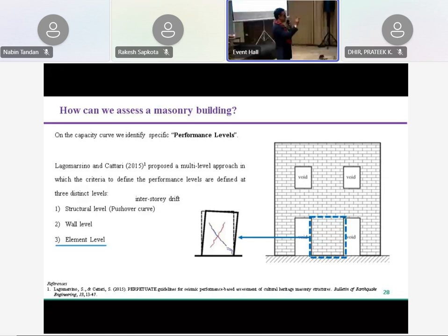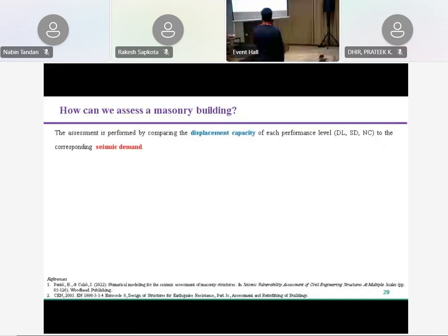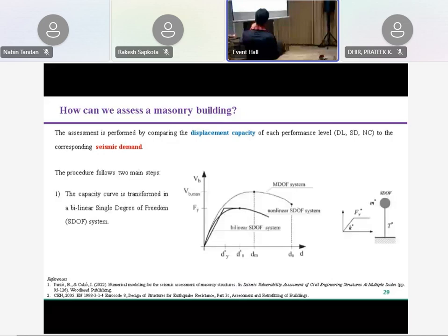Each point of the masonry, I will receive a local information. With the macro element approach, I receive a global information about each element of the wall. So I can look easily what happened at each pier, each spandrel, and then I can identify if I reached any performance level of the structure. And okay, I think I conclude because the next slide, then I want also to speak about the performance level